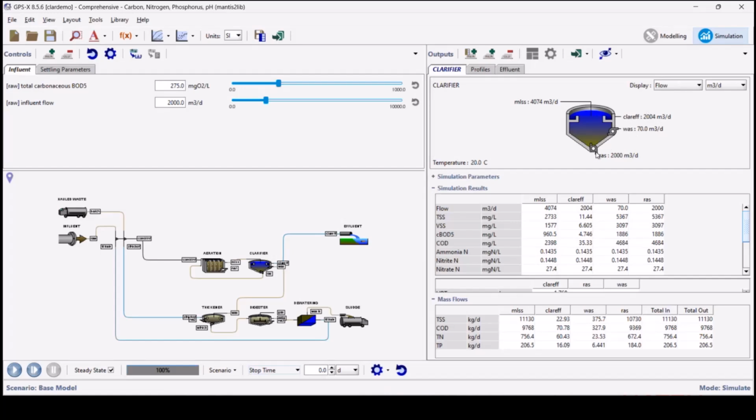We have our wastage, and we have our RAS concentration. So now I've got this already all set up and running and getting reasonably good numbers here. And what I want to show you is that a really nice way to take a look very quickly and see what's going on in terms of solids removal performance, clarifier performance, is to go up to this display here, click here, and pull it down to TSS. So what you'll see is basically this row of the table here, but it's nice to see it laid out in this format.